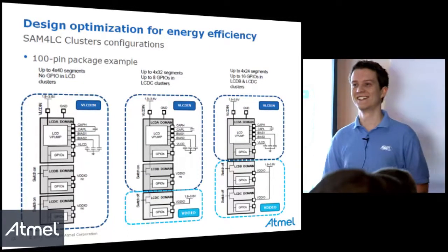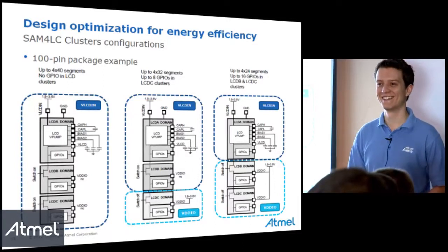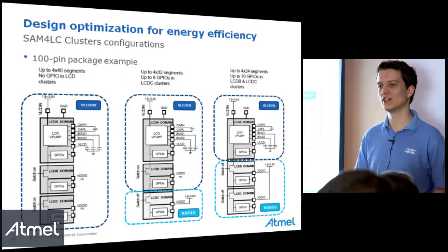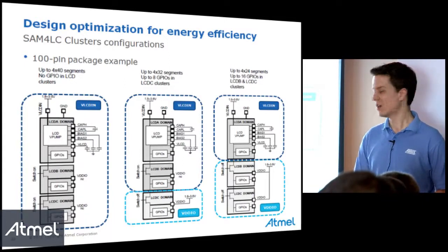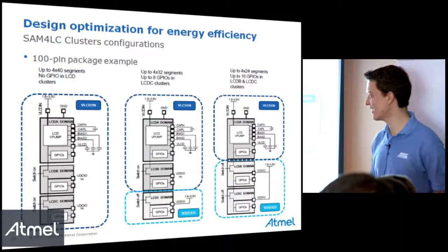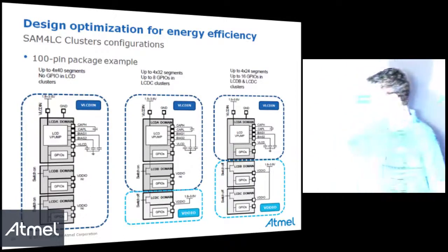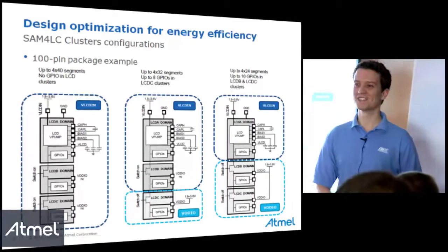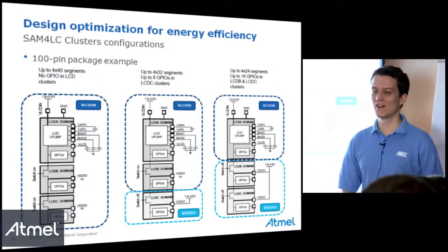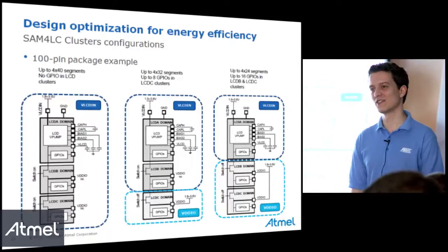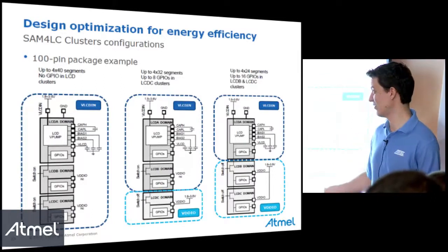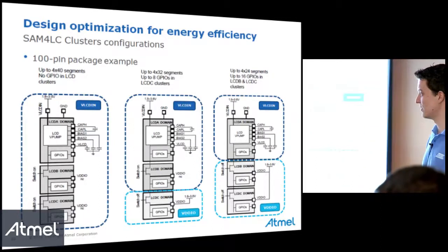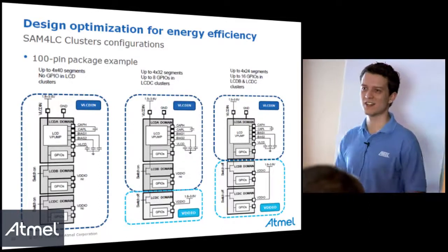Is the version without the LCD controller also three VDD IO pins? No, only this one has this. But that's a good question, I mean this one, the VDD IO pin. I don't know. For me, there's only one. But be careful, the VDD IO level should be the same for all the pins. I need to double check this.